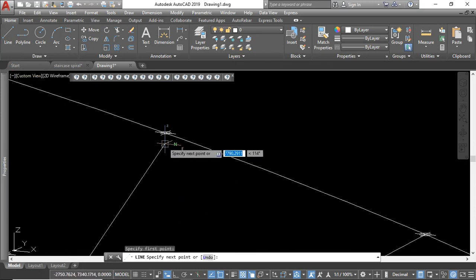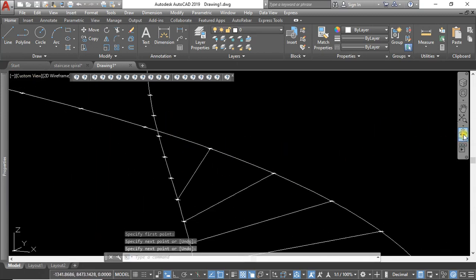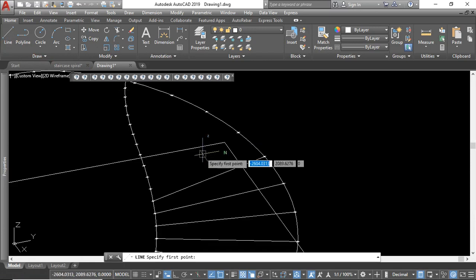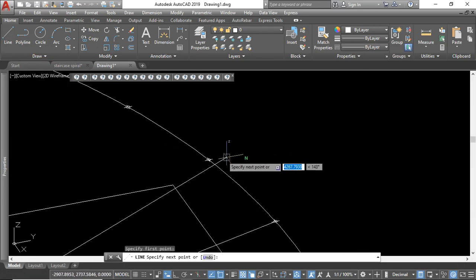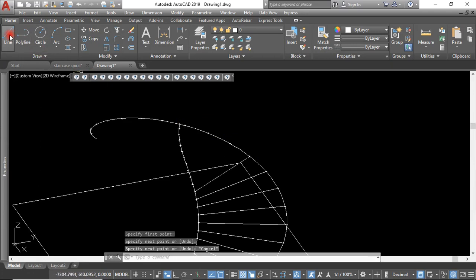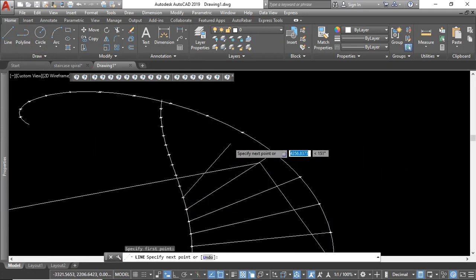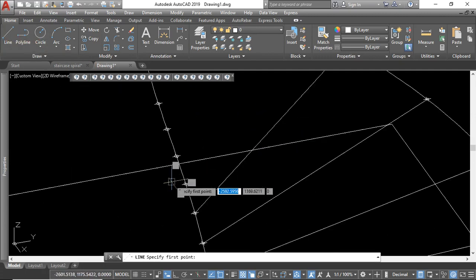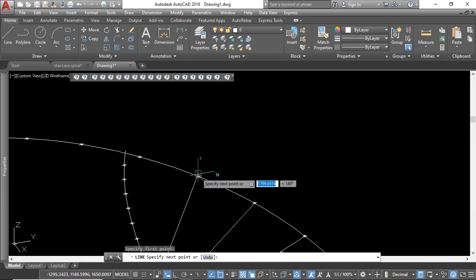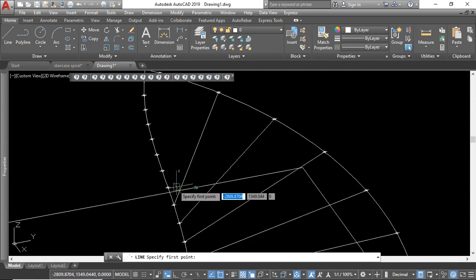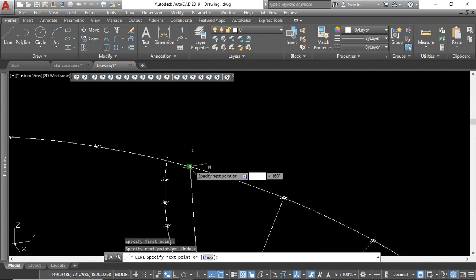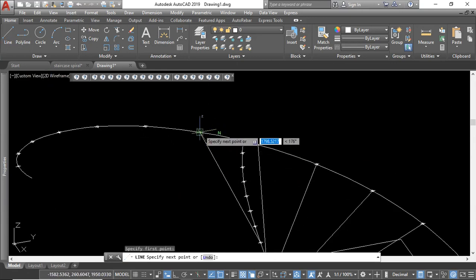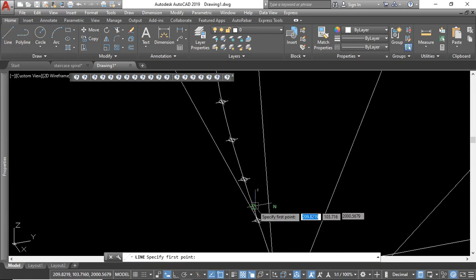And you notice if you don't want to be so much disturbed by this kind of drafting, especially in a 3D space, you better use the line, because line is not dictated like the polyline. So the polyline can just move only in a direction directed by the UCS. But the line makes the drafting easier.